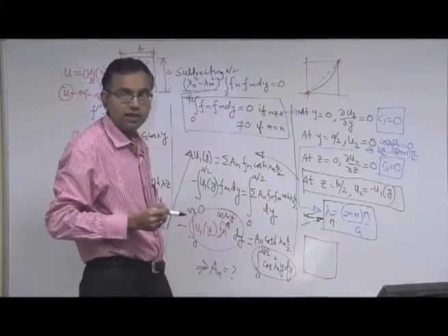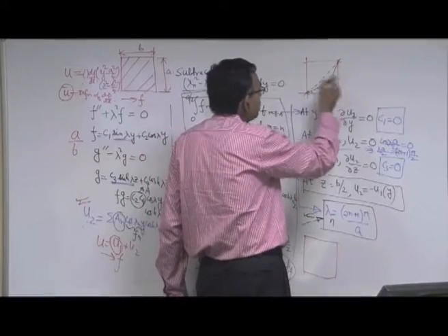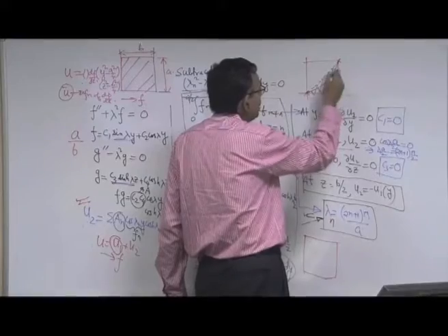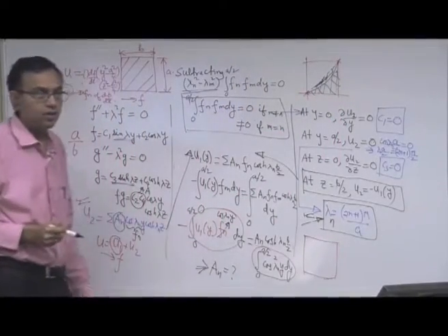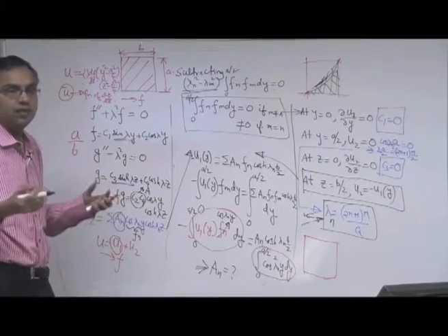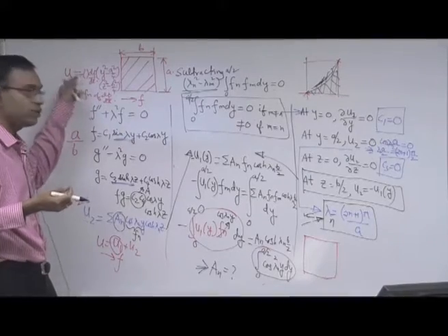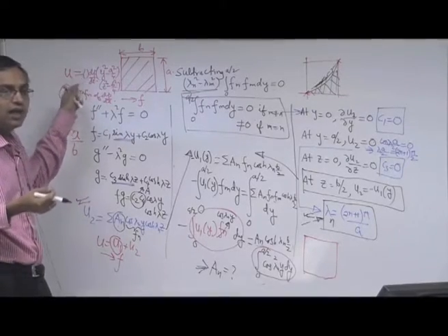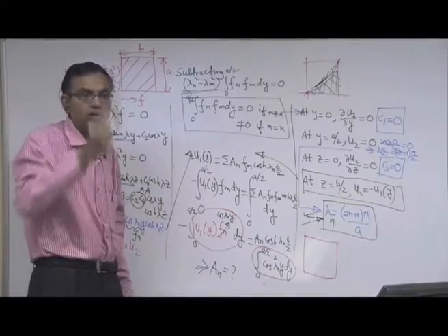So this difference is clear, but the integral requires the area under the curve, for which this little bit of error is not so bad, okay. So we get rid of this error in mathematics because the description through the friction factor requires really the information for average velocity, not the local variation of velocity.